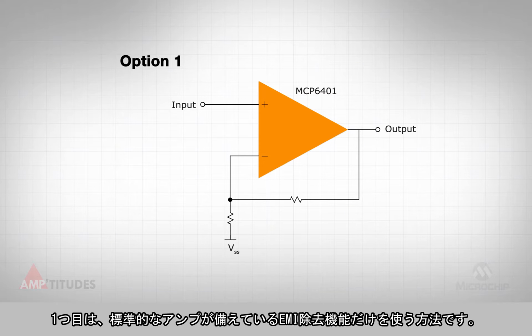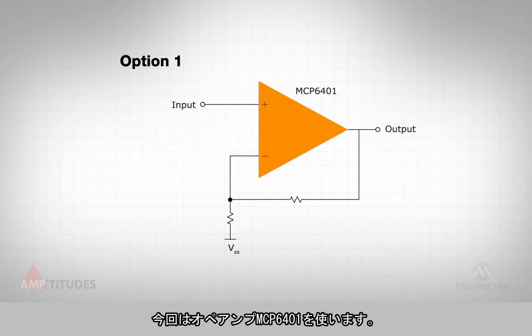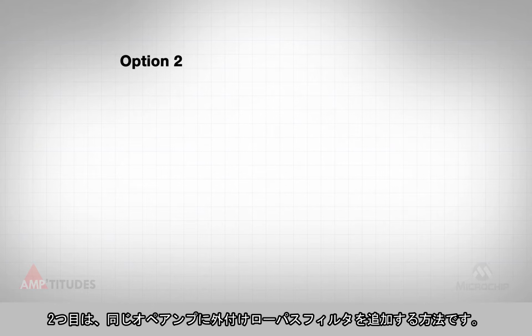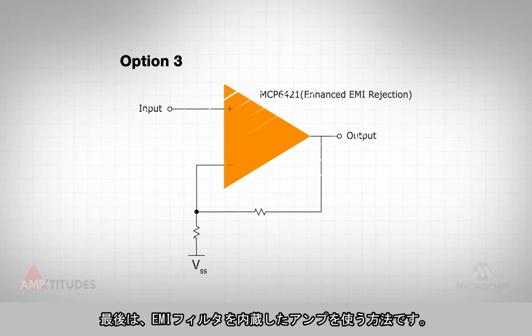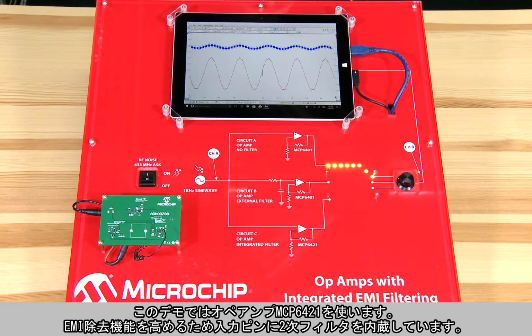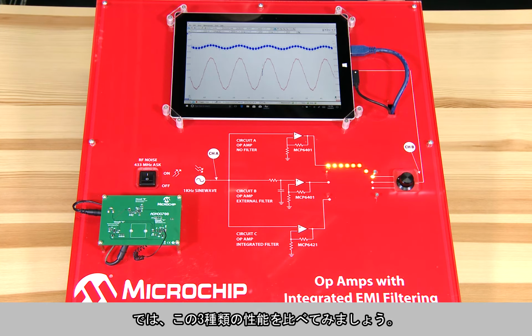Option 1 is to rely on the inherent EMI rejection of a standard amplifier, in this case using the MCP6401 operational amplifier. Option 2 is to implement a low-pass filter external to the op-amp. The final option is to utilize an amplifier with an on-chip EMI filter. This demonstration uses the MCP6421 operational amplifier, which features an integrated second-order filter on the input pins to enhance EMI rejection. Now let's compare the performance of these three options.